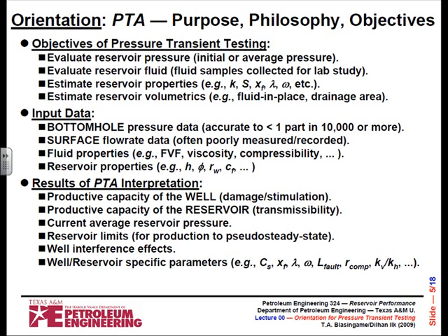Whether it's a production well or an injection well, whether you're producing or injecting, the equations are the same. So you shut in an injector, and you keep monitoring the pressure. In that case, it is going to fall off to the average reservoir pressure. So that way it might work.